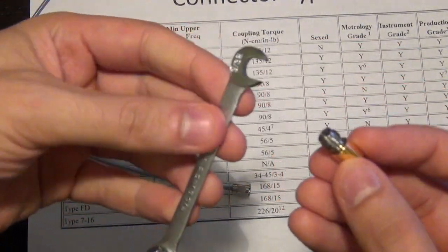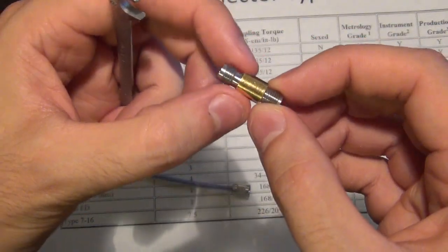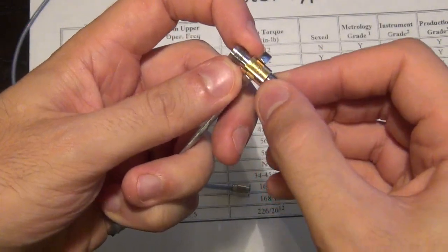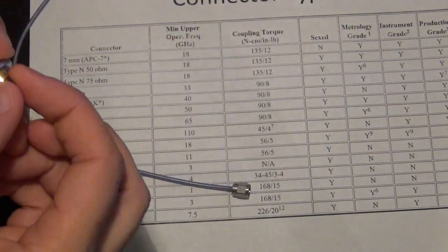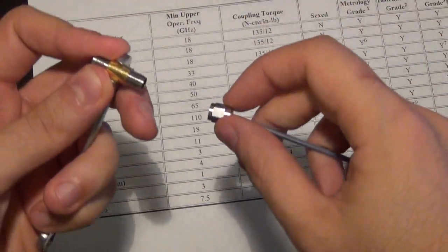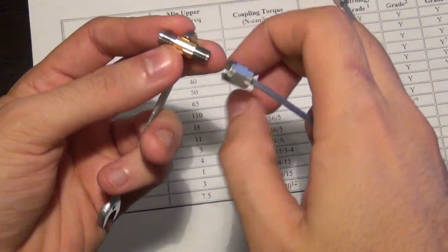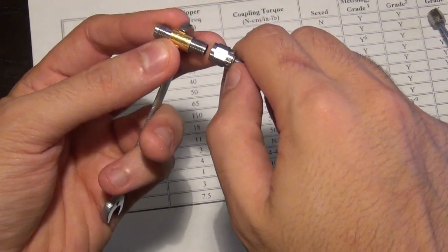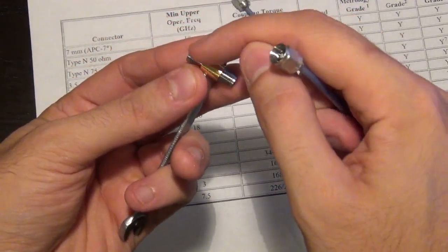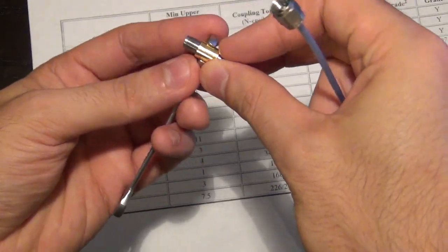A good way to do it is to have a wrench. All of these connectors have a body that has an indentation like this one that will fit within a particular wrench. So this one can be held in here very nicely. You hold this with your hand, making sure it doesn't spin, and on the other side you take the cable very carefully and perfectly centered. You see, for example, right there I was attempting to connect it to the wrong side. So be very careful. I noticed that I was doing it the wrong way because I recognized that is the correct thread. So let me flip this over, like so.